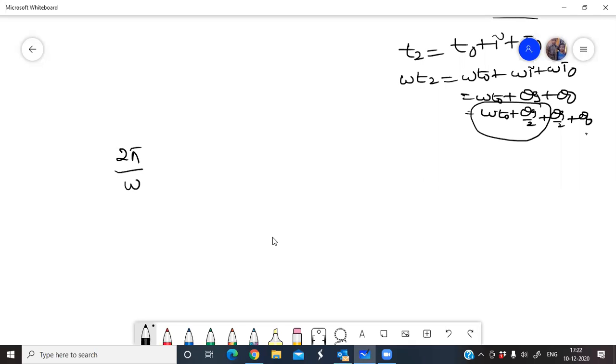Therefore, whenever it is a periodic waveform, you can express that periodic current in Fourier series. So what is the periodic current here? Current is I2 at the catcher cavity, and this current waveform is a periodic waveform with the period equal to 2 pi by omega. So whenever it is a periodic signal, you can express or expand that periodic waveform with respect to Fourier series.